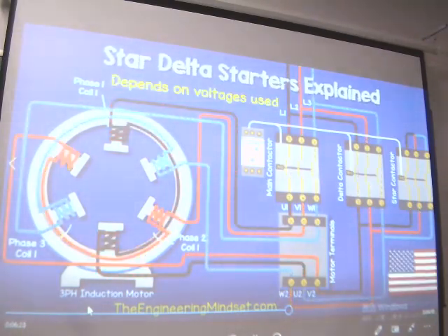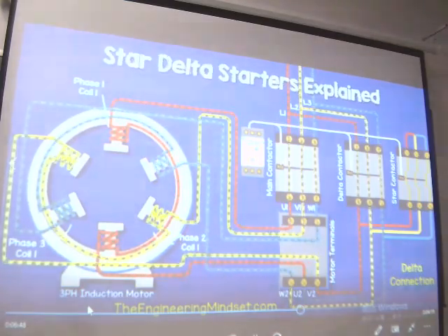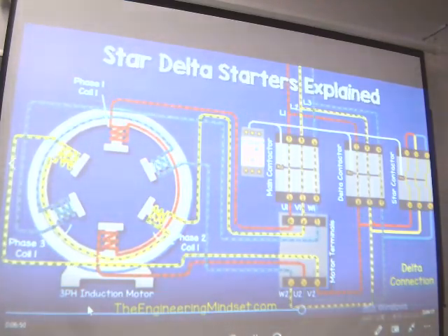If you are in the US, then you might find these colors being used. This is for a 208 volt 3-phase supply, but the colors will be different if you're using a 480 volt 3-phase supply. In the UK, EU and Australia, you'll find these colors used for the phases. Yes, if you're in the UK, then you're probably still going to come across versions of the red, yellow, blue colors being used. This is an old, outdated color system, but old installations are still going to exist.